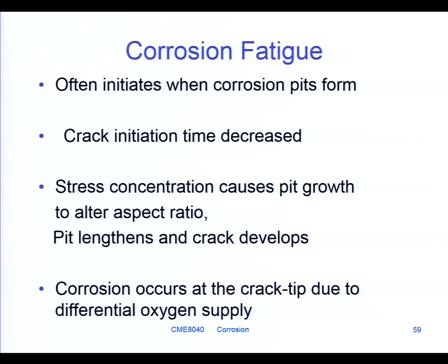For corrosion fatigue, that initiation time is significantly reduced because you're beginning to enhance the stress concentration on the surface by the corrosion effect. So in this case, the life of the component is going to be a lot shorter than the life under air fatigue, because the crack starts early.